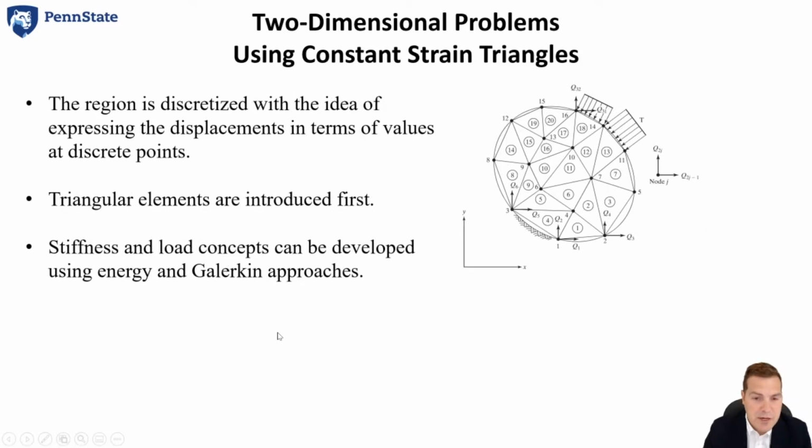Of course, we're going to discretize this like we did in the 1D problem. So we have now our potato-shaped object, and we fill it with triangles. Just like in 1D, we had to discretize the shape here, so you can see the triangles fill in this shape pretty nicely. We do have these gaps that are left just due to discretization and the straight-sidedness of the triangles. So if we wanted to reduce that, we would refine our mesh here, and we could cut a sliver in half, and have a better representation of the geometry.